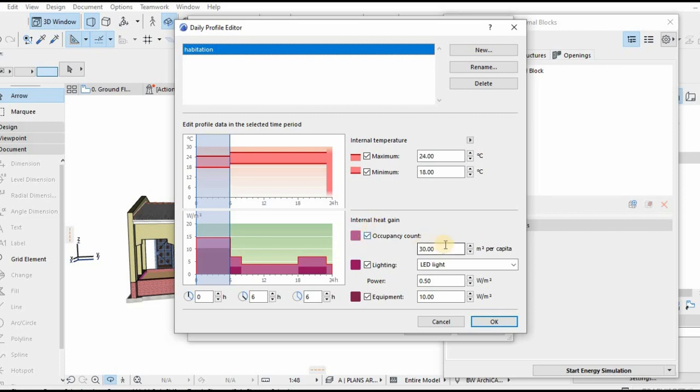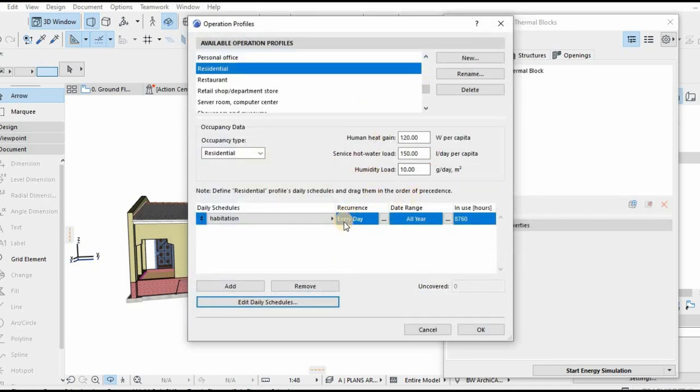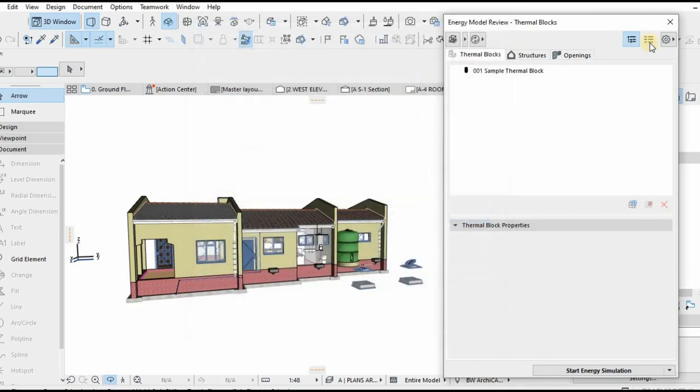Okay, and then what you do, so this residential house, let's say 25, it's a 3-bedroom house, it's not a big house. And then the lighting of the house, define it: is it incandescent, fluorescent, composite, so you can define it here. Then equipment power, there's a lot of equipment, or is there little equipment? So yeah, you feed in this occupancy behavior, occupancy type of the house. That's the starting point.